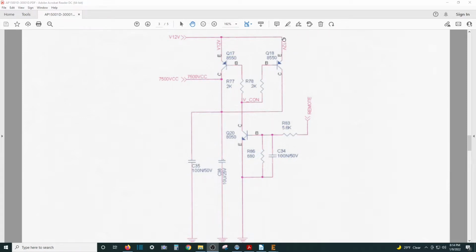And this one's actually paired. A lot of amps will not have this second one. They'll have just a bigger transistor. They've used small surface mounts. These are PNPs. And the way I always tell is the arrow always points towards the negative. So this would be NPN, because you got a negative here in the middle on the base. So this is going to be a PNP. But it turns on a pair of them through these two resistors to immediately pull these on. So that takes this 12 volt. When these transistors are turned on, they'll pass 12 volts through. And you notice they join at a little dot right here, which is the same little dot that goes out to power the chip.